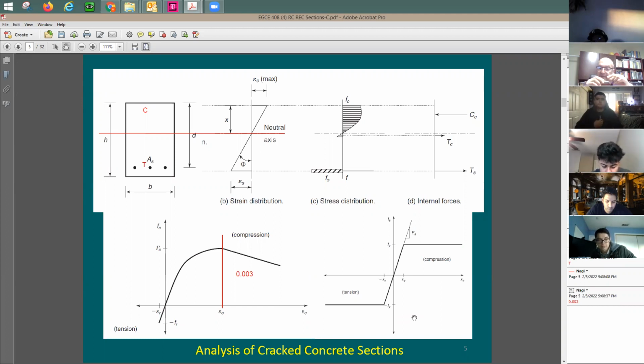So as long as the rebar itself is contained in concrete and is prevented from buckling, you're going to have similar performance in compression and tension for the steel. We call this the yield point, f_y. The slope of this line is 29,000 ksi, standard for all steels. This is going to be the modulus of elasticity, E_s.